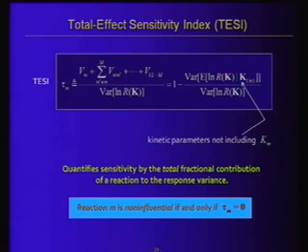So if I calculate these indices for my network and I identify those taus whose values are small, by the way, the values of tau are between 0 and 1. This is another nice thing, where in terms of the derivatives you don't know how big or how small they will become. So if you set up a threshold, everything below that threshold will correspond to non-influential reactions based on this.